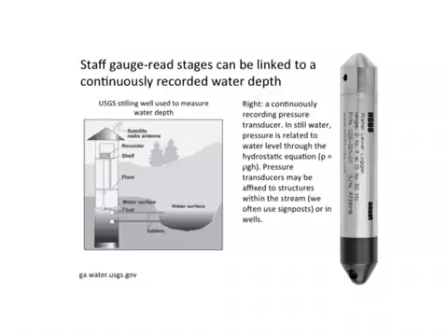Then finally, at USGS gauging stations, which again are often located around bridges, there will be an instrument that can measure water depth in an automated fashion and record values of water depth continuously. I have one. This is a photograph of the type of pressure transducer that I have, and it's based on the fact that we can establish a relationship between hydrostatic pressure and the depth of water.